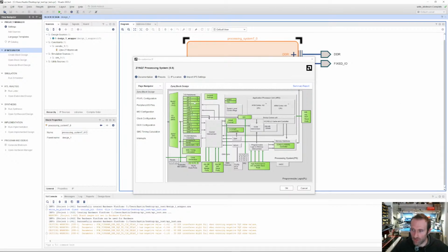This is the beauty of working with a Zybo board or these types of chips: you can route SPI and I2C and whatever out through whatever pins you want. More specifically, you can route whatever you want out of the chip. If you make a board like the Zybo board, they have those copper traces routed to specific headers.